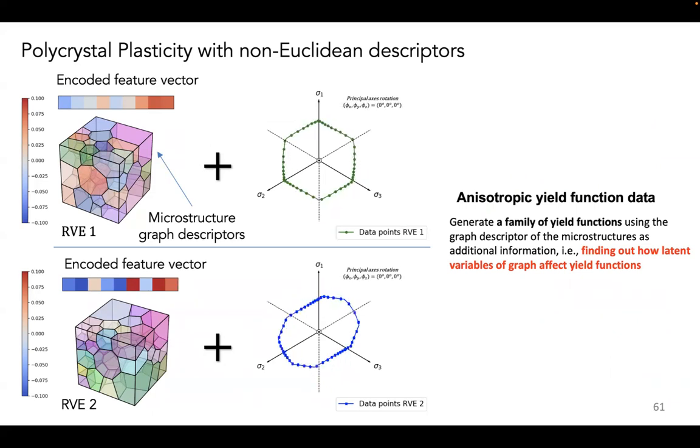If I want to complete the entire constitutive law for each orientation of the crystal, I need a particular yield surface, and then I link them together. You understand what I'm saying? Just imagine that I have a Drucker-Prager model. Basically, it's a circle on the pi-plane, but it depends on the pressure. So you can stack those instances together and then compute it.